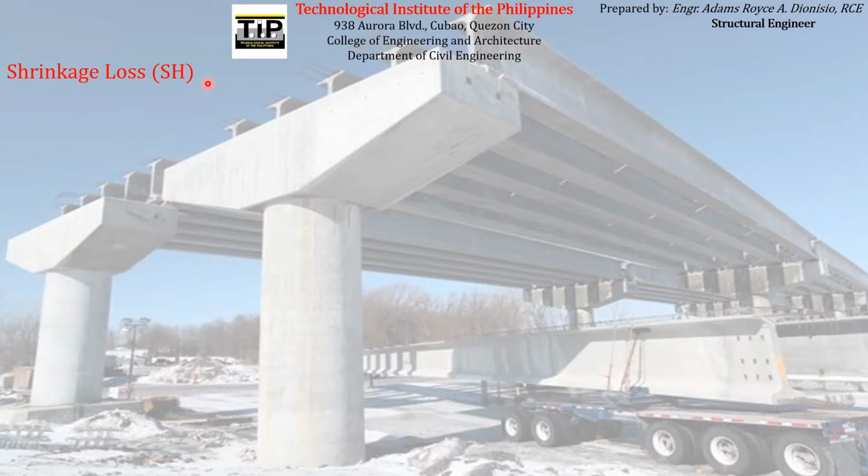And that shrinkage phenomenon that is being experienced by the concrete when water moves away or moves out from it results in what we call shrinkage loss that is being experienced by the pre-stressing reinforcement.